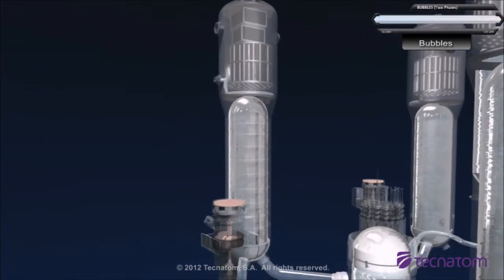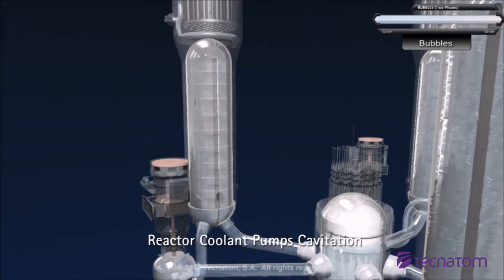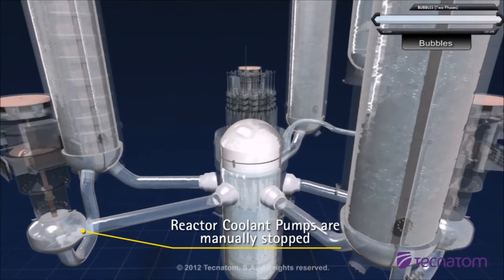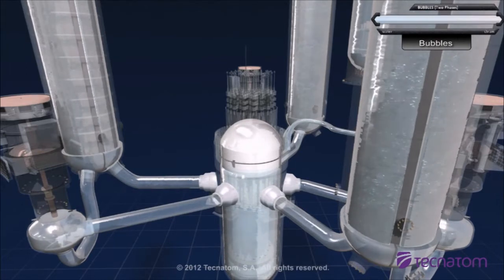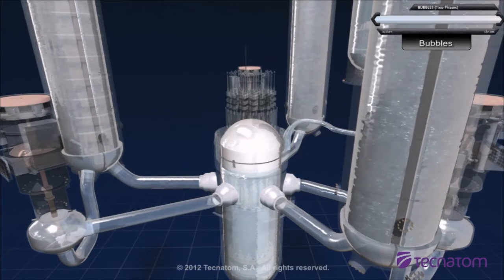Steam bubbles are pumped through the primary circuit. Reactor coolant pumps are not designed to pump steam, and they start cavitating. Pumps are manually stopped at this point for pump protection purposes. Circulation of bubbly water through the core stops, and the core cooling is severely affected.